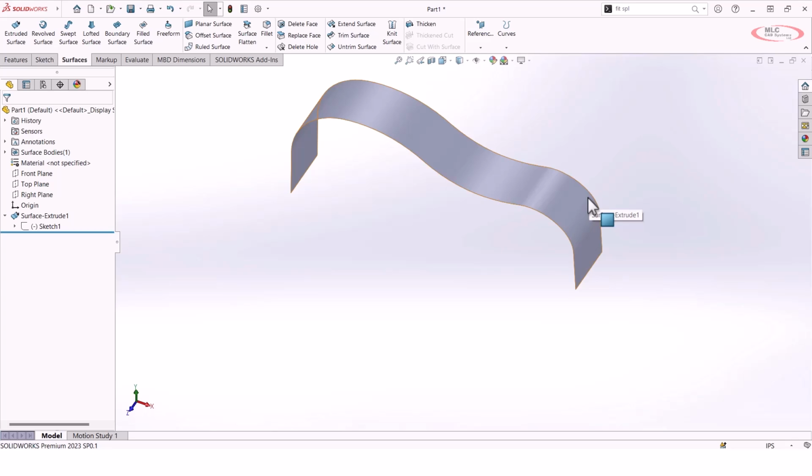So keep that fit spline option in mind. It definitely lets you work with simpler sketch tools and then convert them to a spline once you're ready, and it can give you some really robust surface bodies with relative ease.